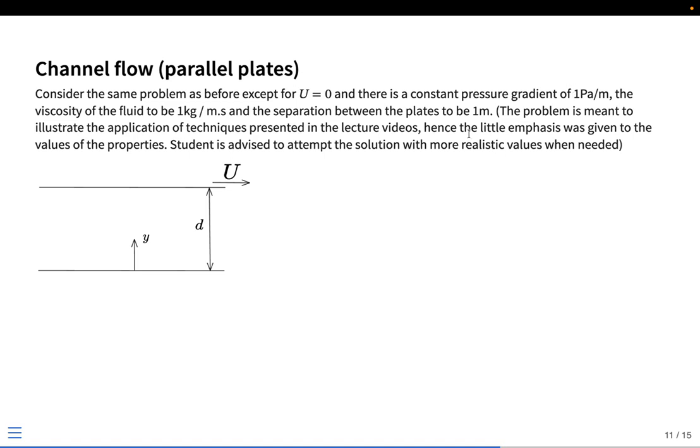All the values are taken to be 1. So if I were to write the governing equation for this, it would be similar to what we had before, just that the only difference is now we have a pressure gradient term, so this will be minus dp dx equal to 0. Again, this is something that we have already solved before, so I'm just telling you that this is a constant value. So you can take that to be some constant, d square u dy square